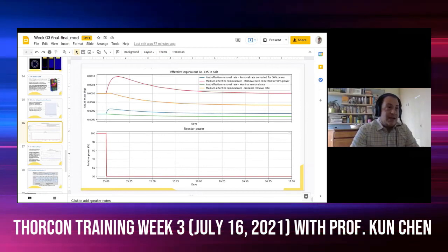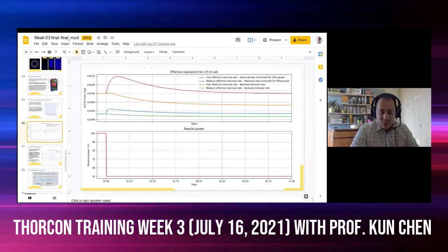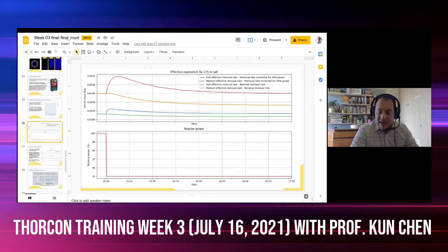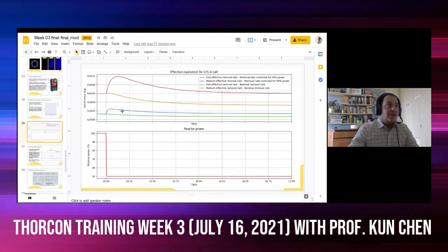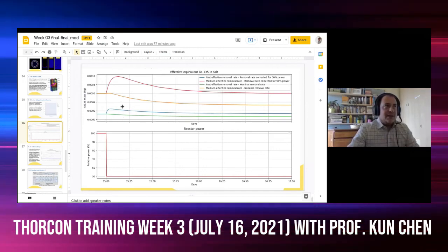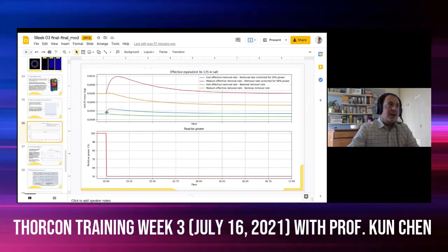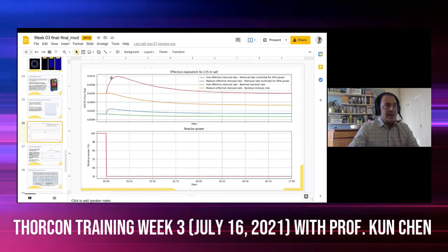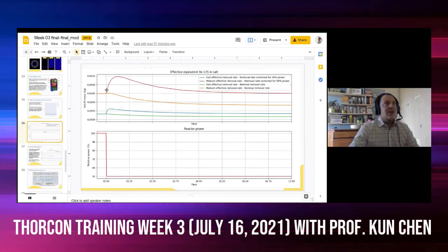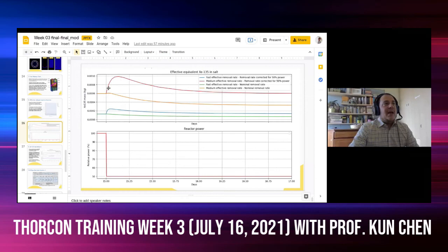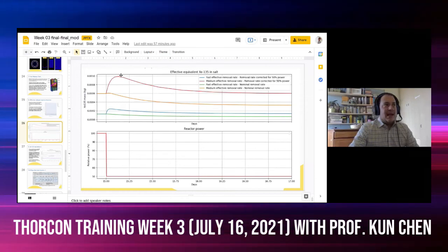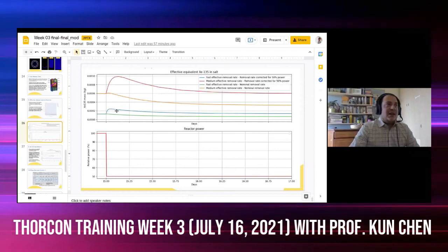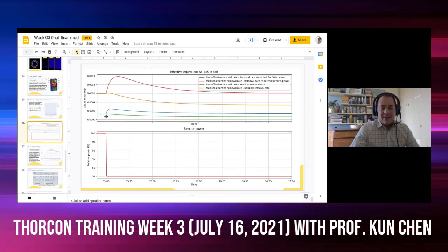In our case, though, the main path for the removal of the xenon is through the header tank. And we have two assumptions in this specific case, a fast effective removal rate or a medium effective removal case. And you're right, in the medium case, the peak happens within the 6 hours after the change in power. In a fast removal rate case, it happens even before.